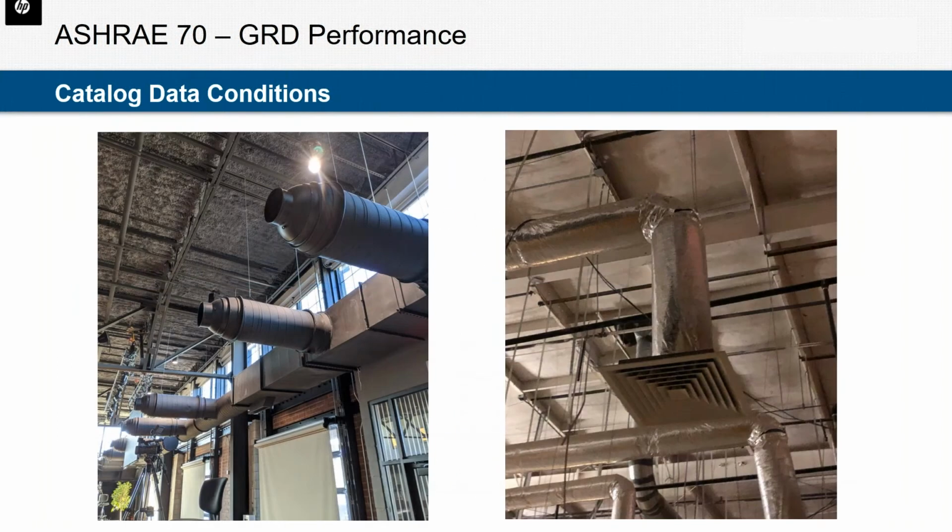So what I like to show are a few examples of how that changes the product. Here's a couple of examples I've found from my own travels of diffusers following this advice. Sometimes it's at the expense of the architecture, where you can get your 3 duct diameters, but it might not always look good. Sometimes if you have a large ceiling, you can afford the space, such as the picture on the right, where we do get 3 duct diameters. Now, granted, personally, I don't think this louvered face diffuser exposed in the ceiling like this looks great, but it is probably performing as expected.